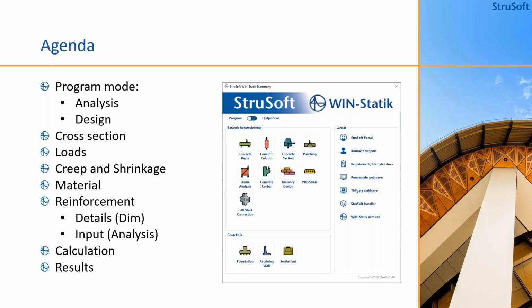If we take a look at the agenda, what we are going to talk about today is concrete section. This is a small program that will be calculating reinforcement using the section forces. It is possible to analyze several different sections for one set of forces. We will go through the analysis part and the design part.